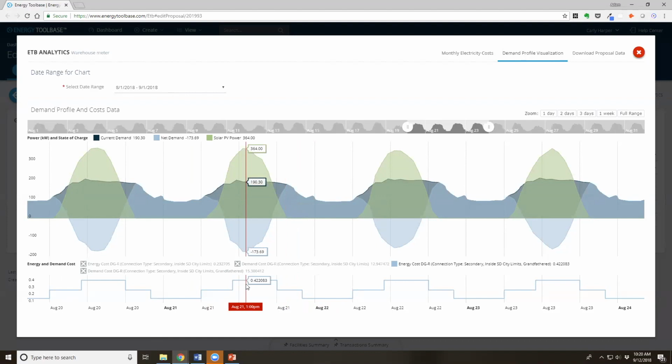This again was the November of 2017, or also the grandfathered rates of today. But what I really want you to key in on is the bottom of the screen. You can see that the on-peak window had previously been defined from 11 a.m. to 6 p.m. And you can visually see how the solar production curve, this happens to be a fixed tilt solar production curve, lines up pretty nicely with how that 11 a.m. to 6 p.m. window previously was defined.